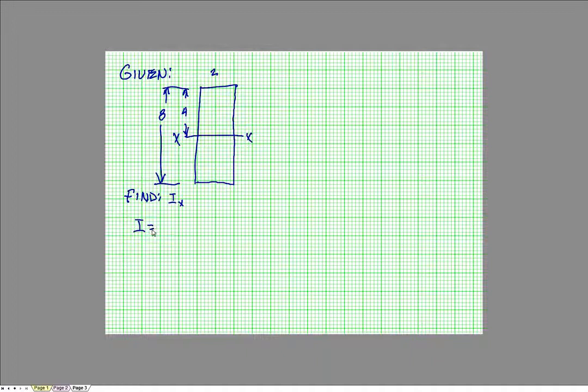So moment of inertia equals the summation of area times y distances squared. Our y distance is from the individual centroids to the overall centroid, and in each case that's 2 inches. So that is area, and they're exactly the same, top and bottom.